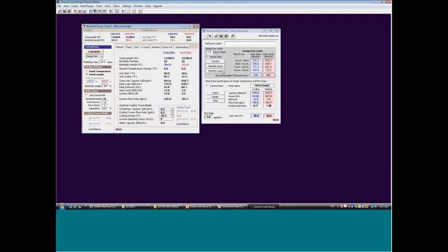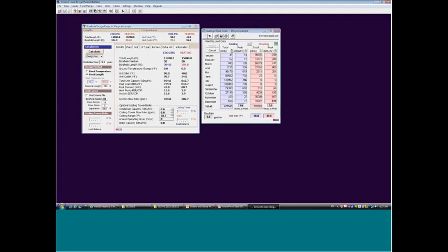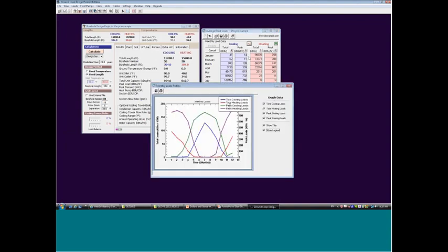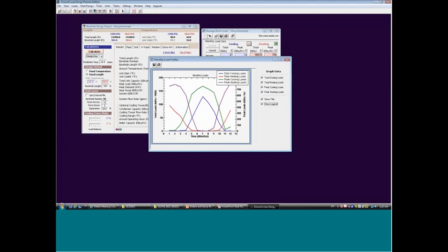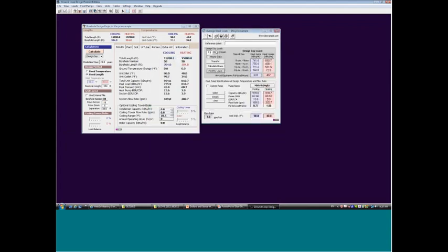I'll go to the monthly loads tab. You can see my total cooling is about 478,000 kBTU for the year. My heating total is about 370. So it's cooling dominant, but not excessively so. It's a reasonably balanced system, although not perfectly balanced. You can graph the loads data and get a sense of it that way. I chose a heat pump, a pretty modern, mid-sized, 4 or 5 ton, pretty high efficiency heat pump. I designed my loop field.